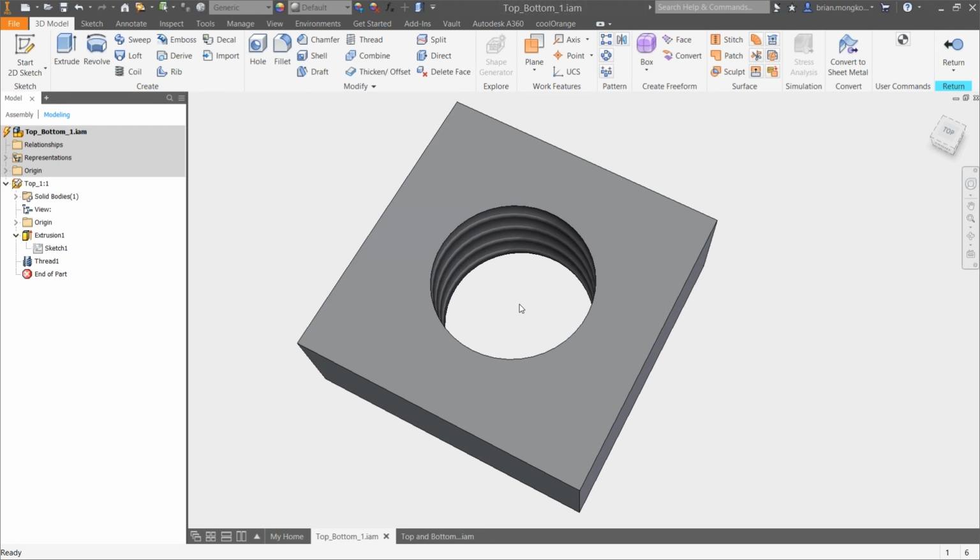If you think about how a thread is, not manufactured per se, but how threads are visualized, right? That's not one continuous face per se, because of all of the curvatures and the edges and all that other stuff. So it's going to be super, super heavy is the term that we like to use around here. The file's going to be super heavy. It's going to start grabbing all of your RAM, and then you're going to complain that it takes too long.